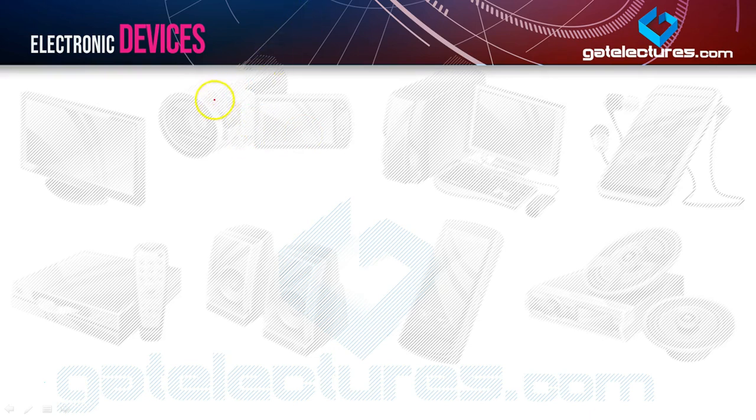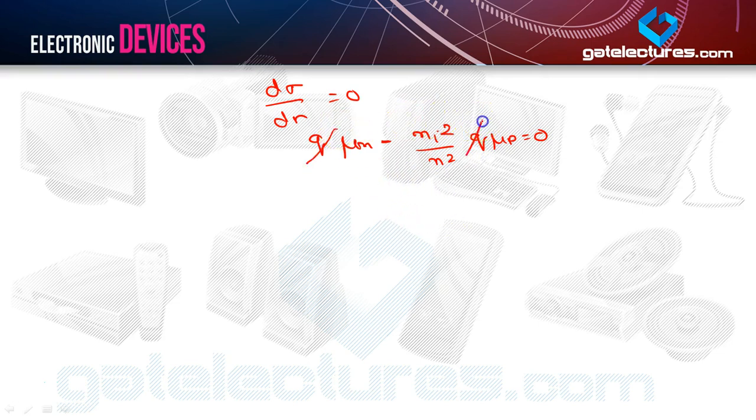So for minimum conductivity we equate d sigma by dn to 0. We get q mu n minus ni square by n square q mu p equal to 0. The q cancels.